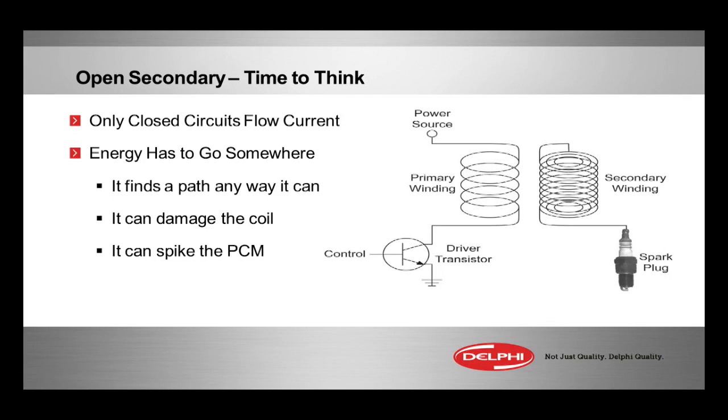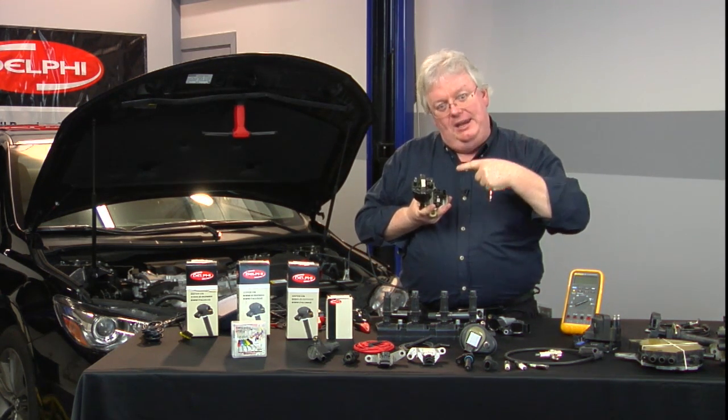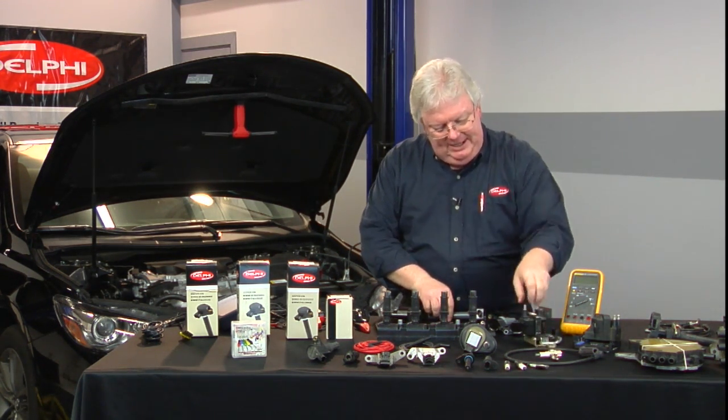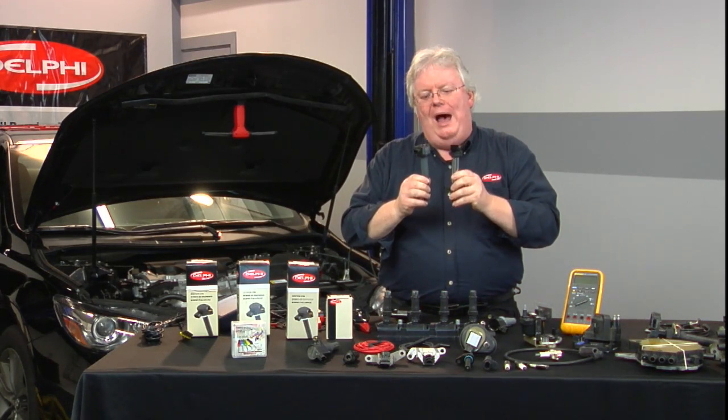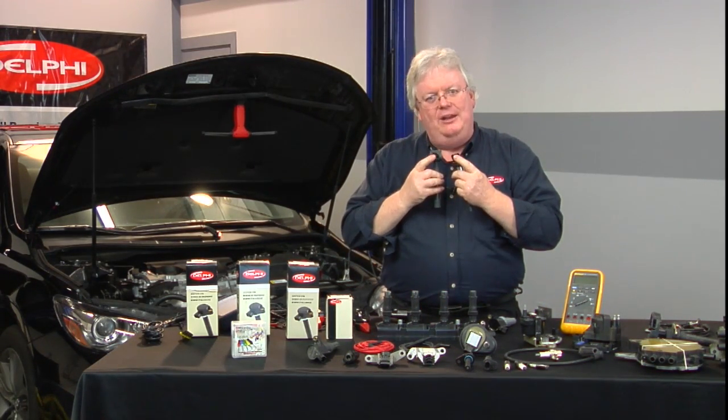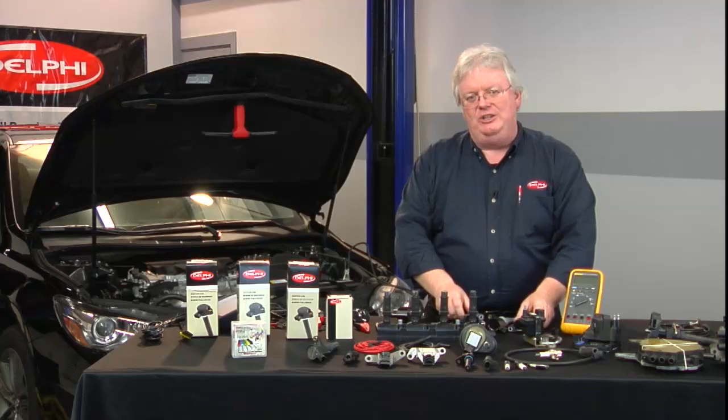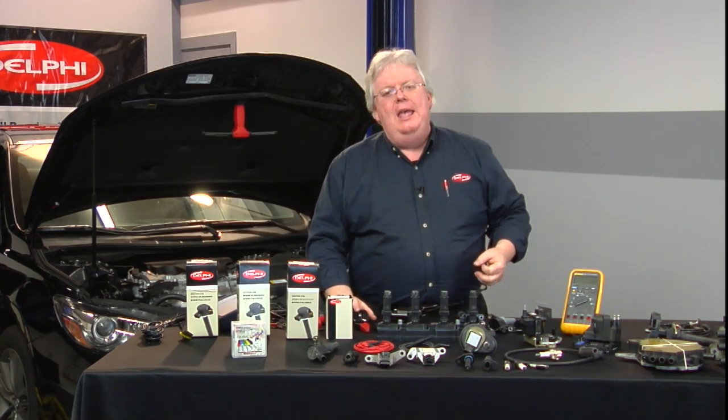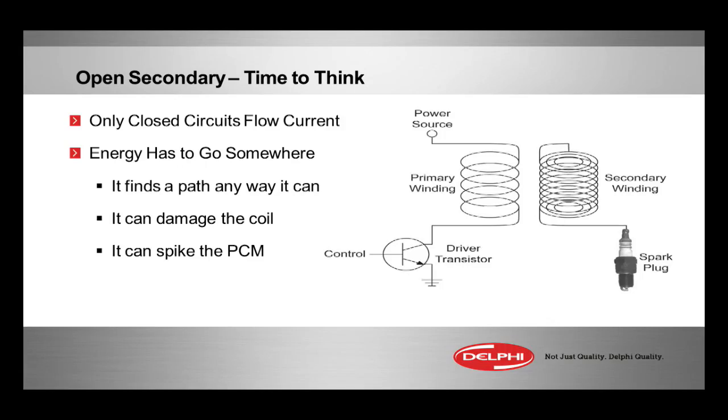So think about it, if you got more than 2 wires, you got 2 functions here. You have basically an ignition coil and an ignition module. That's what's in all of these that have more than 2 wires to the connectors right here in the harness. They are ignition modules and coils built into one. And so what can kill an ignition module? Well, high voltage spikes, EMI, bad grounds, intermittent power sources.